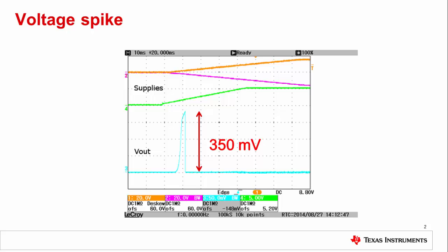The cause for a power on glitch within the DAC can be due to a couple of different reasons, depending on the output topology of the DAC. The 350 millivolt depiction shown here is actually a very forgiving scenario. Sometimes you can see 2 or 3 volts at the output. Let's look at the how and why of a DAC producing this error.